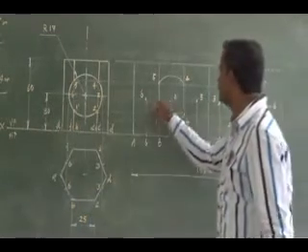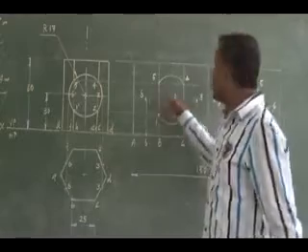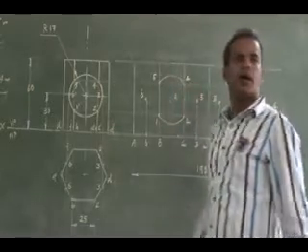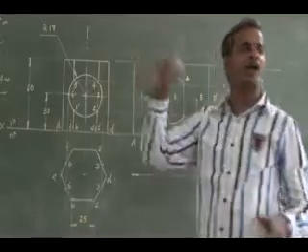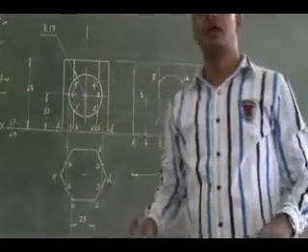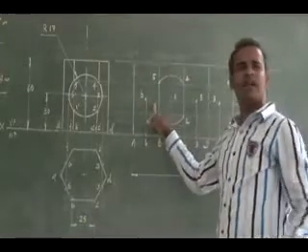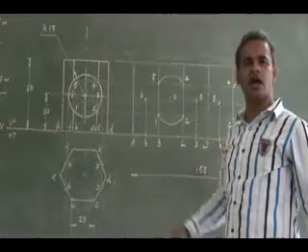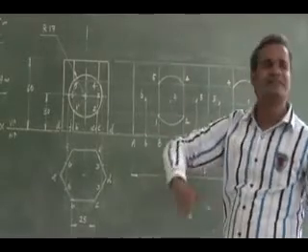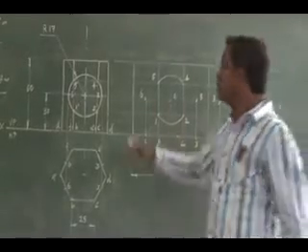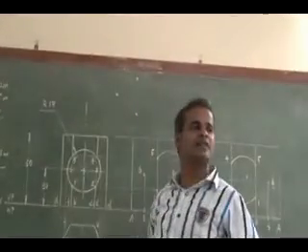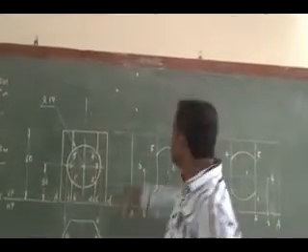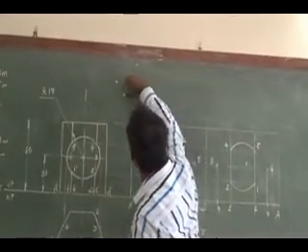Right. Now you see, I have to connect 1, 6, 3 as an arc. So this arc will not have a radius of 17. Isn't it? It won't have a radius of 17. It will be a different arc. So you have to draw it as a 3-point arc. Okay, I have 3 locations. I have to connect it with a 3-point arc. Right, 3-point arc means it will have a different radius.